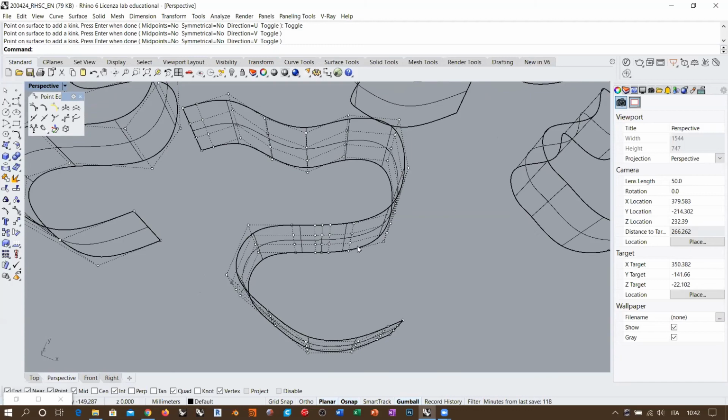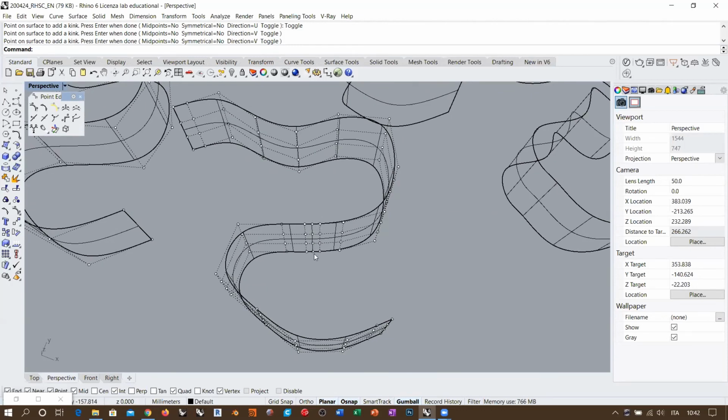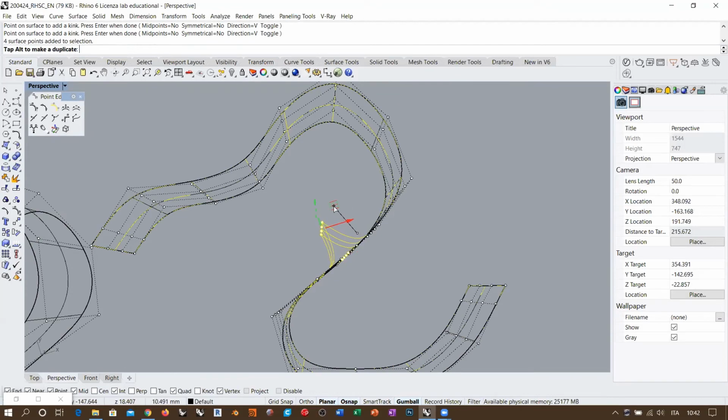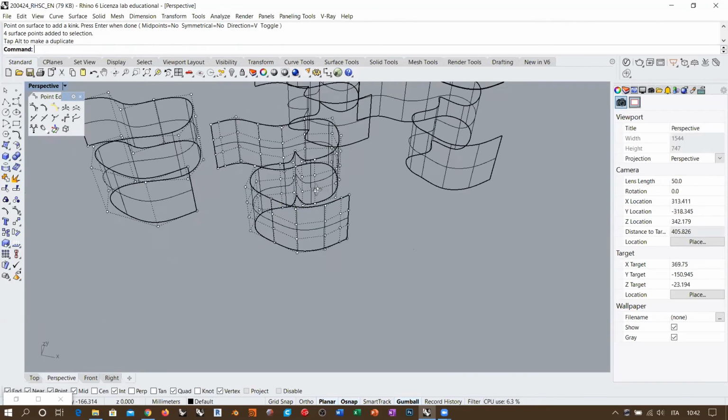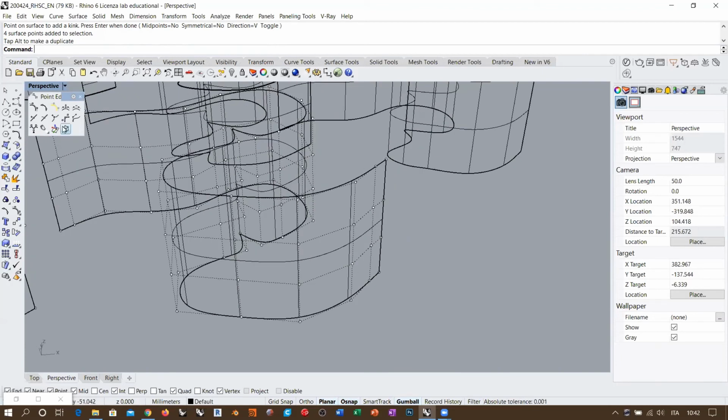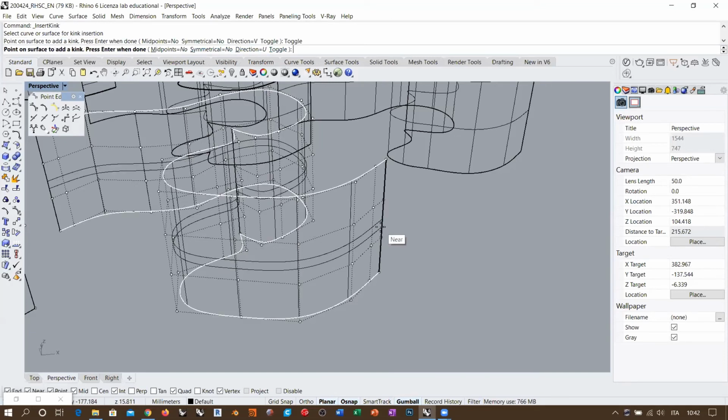You see that now all the vertical lines have 4 control points because we have already changed the degree of our surface. We can create this kink deformation here, but we can also create internal kinks horizontally. And as this is a degree 3 interpolation in the vertical direction, we will also have some kind of organic deformation. Oh, by the way, we have 4 control points and actually one visible horizontal isocurve.